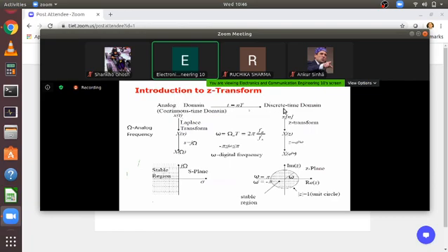That means the discrete time signal. You replace the t values with nT, where T is the sampling interval. Now, in the analog domain, what do you do? In the analog domain, if x(t) is the signal, you apply the Laplace transform. But in the discrete domain, if x(n) is the sequence, after you sample the signal and make it a discrete time domain signal, you apply the Z transform to get